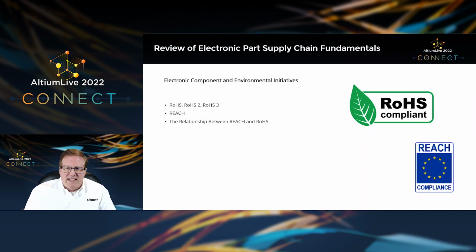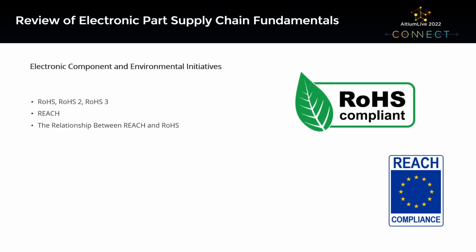RoHS does not affect the application of REACH and vice versa. With regard to the restriction of substances in electrical and electronic equipment, when there is an intersection of the two initiatives, the strongest restriction, for example, the lowest maximum concentration, should be applied.